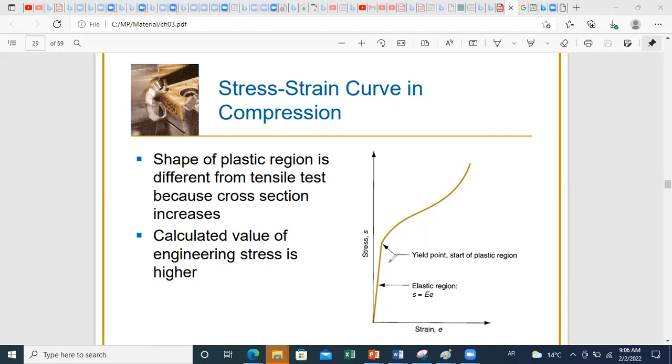So already we can detect an elastic region where the engineering stress is varying with strain, and as I told you, when you present a positive value, you put just C for compression to say that it's a compression test. Or you can just remove C and put a negative value.